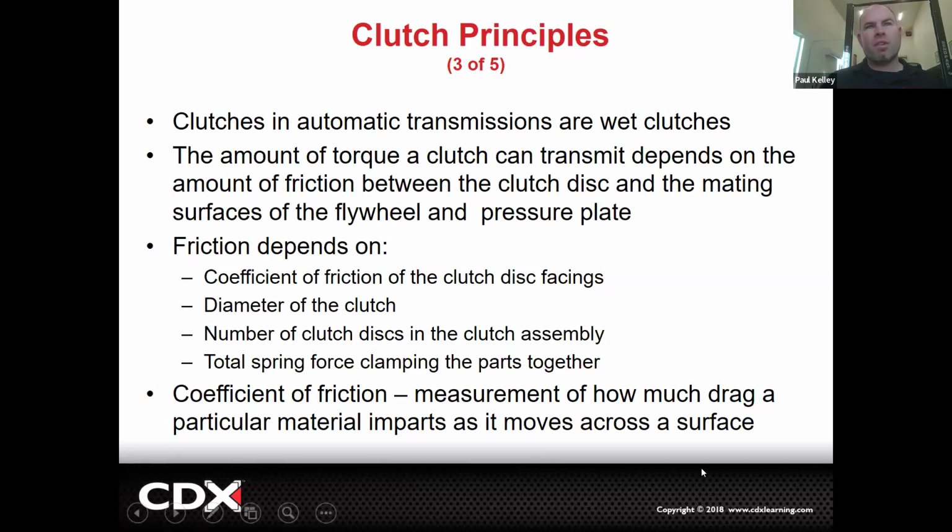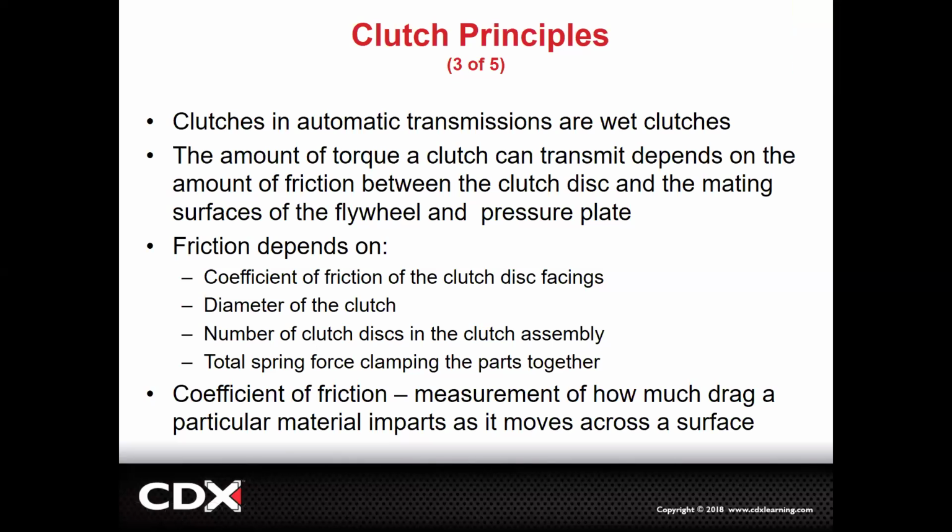Can anybody think of one negative? If you wanted to have a clutch handle more torque, can you think of one negative of having it handle more torque by putting a stronger spring in there? It's more difficult to drive day to day. Exactly.